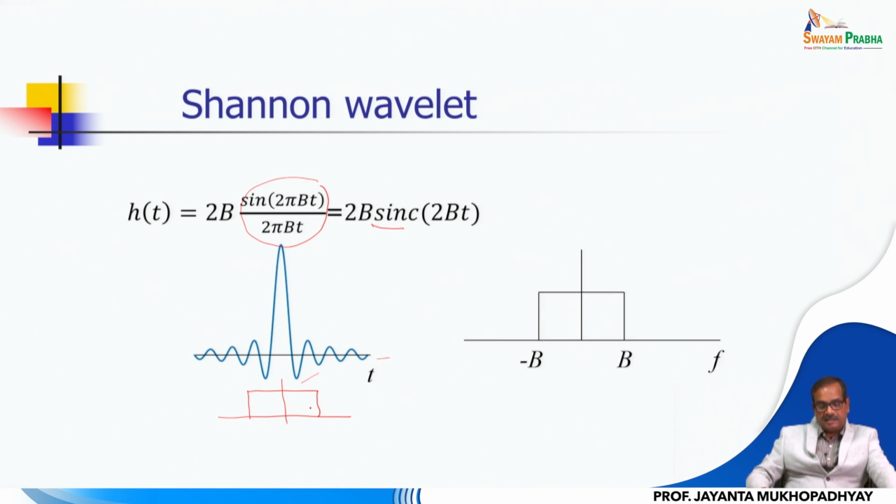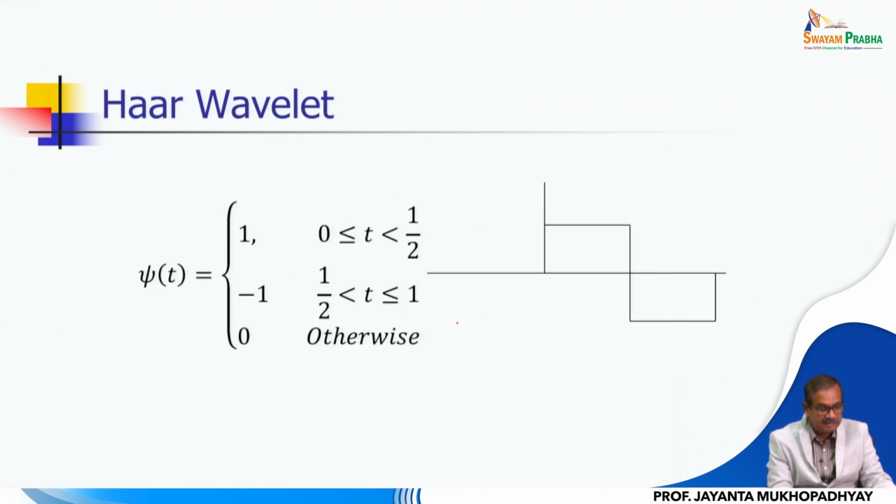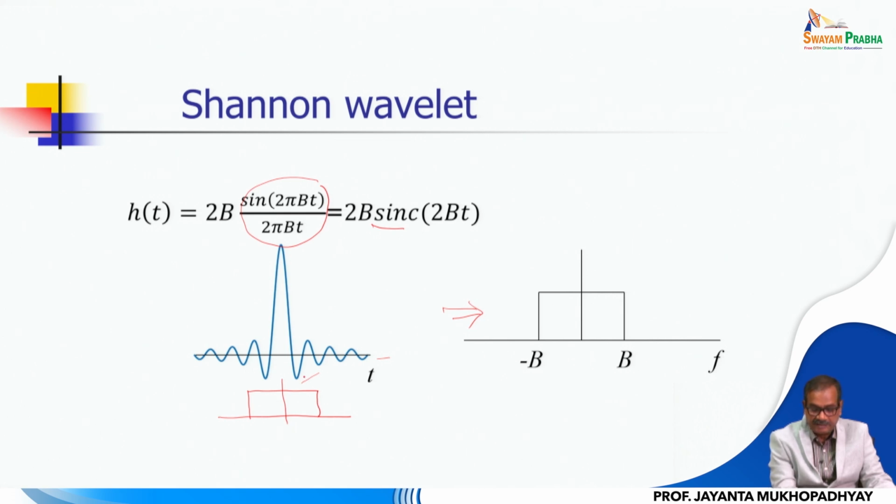So this is the frequency domain representation of the sinc function. As I was saying, this function itself could be a candidate for a wavelet. We are not going to take any product, only this property, since it has practical finite support in the time domain, and also its respective support in the frequency domain, which is ideally, I mean theoretically, a finite support.